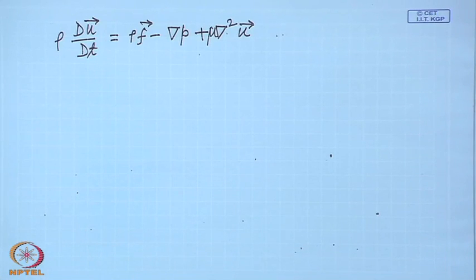And also at this stage perhaps I should mention something about this pressure again. If we use the thermodynamical equation of state, the common example, the equation of state for a perfect gas, as you know, P equal to rho R T. Now, we have already mentioned that the pressure as defined in thermodynamics as a state variable is not the same as the way we have defined the pressure here, which we have taken as simply the average of the sum of the normal surface stresses.